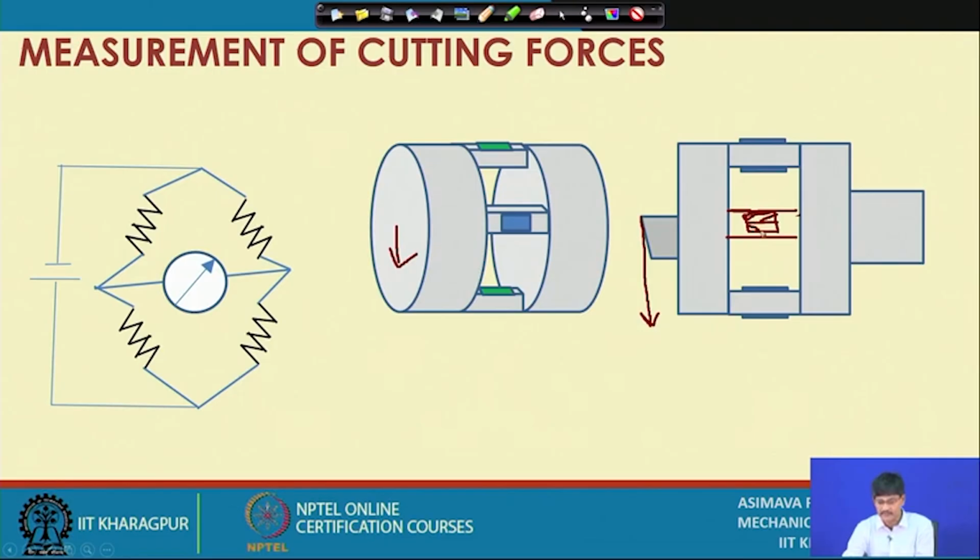In this case, however, it is below the neutral axis and it is going to register a compressive stress, and resistance is going to become less. However, if you consider this particular one, it is definitely going to be tensile. This particular one is definitely going to be compressive. This one also, since it is more towards the top, is tensile, and this, more towards the bottom, is compressive.